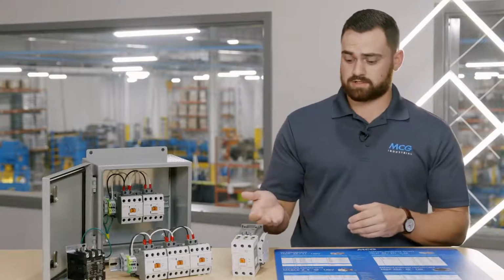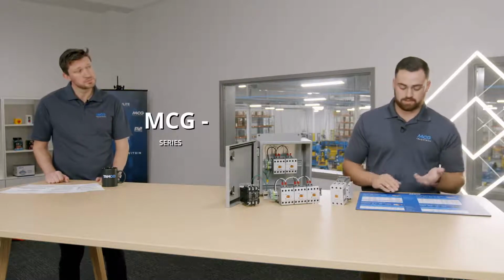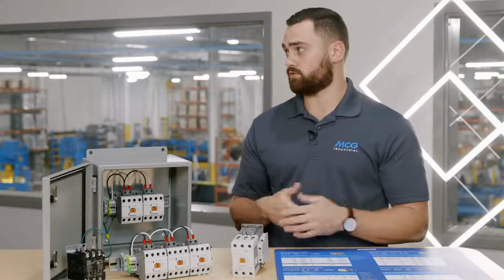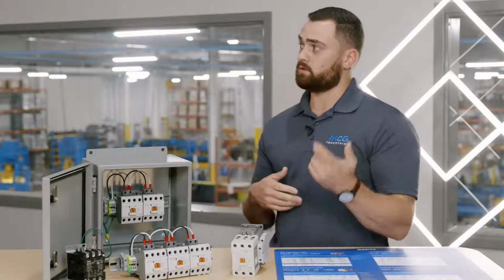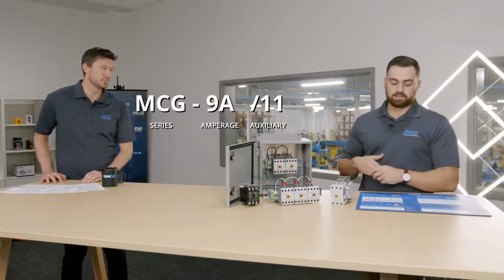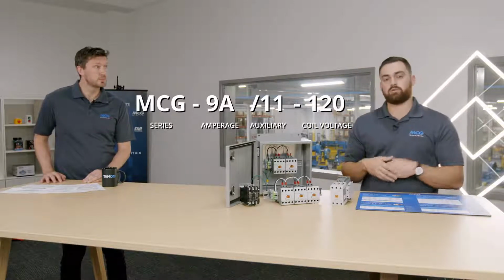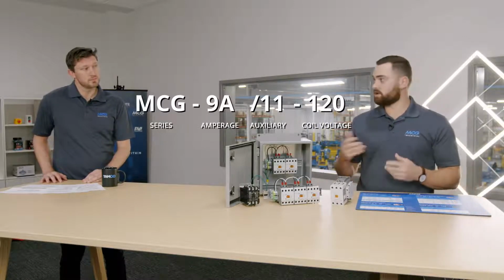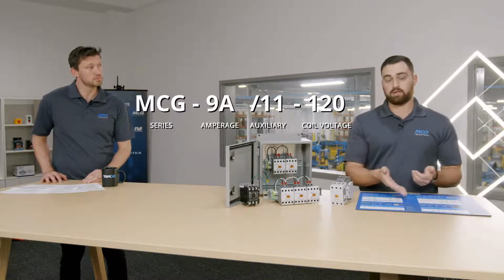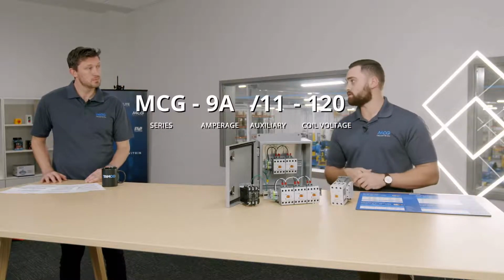So the matrix starts out with MCG, followed by the amperage, which in this case is 9 amps. And then the second question that you could ask would be, okay, what's the auxiliary that you prefer? If it's just one normally open and one normally closed, that part number matrix is going to be 11. And then it's going to walk right into the coil voltage, right? So let's say the coil voltage is 120. That would be the last part of that part number. And the part number that we just went through together is MCG 9 for 9 amp, 11 for the auxiliary contact option, and then 120, lastly, the coil voltage. Simple.